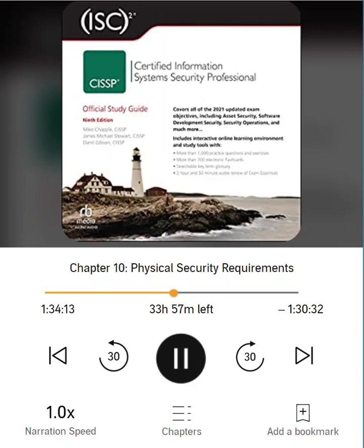To be effective, fire detectors need to be placed strategically. Don't forget to place them inside dropped ceilings and raised floors, in server rooms, in private offices and public areas, in HVAC vents, in elevator shafts, in the basement, and so on.